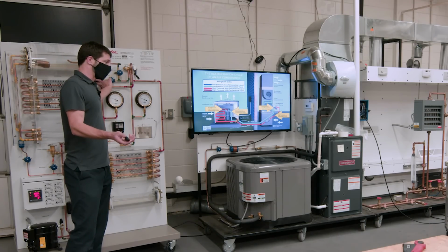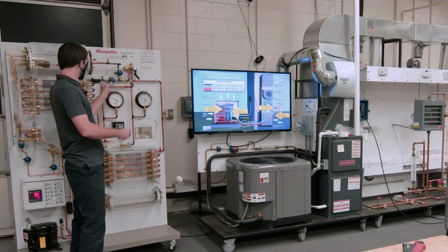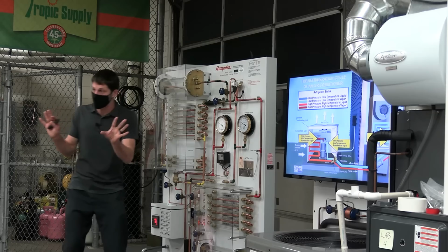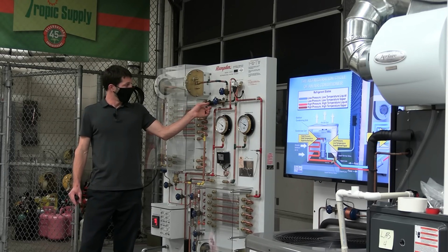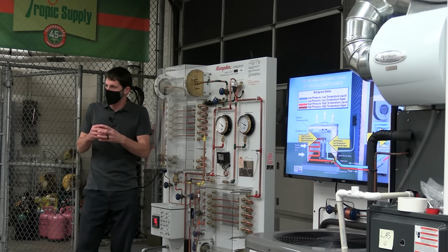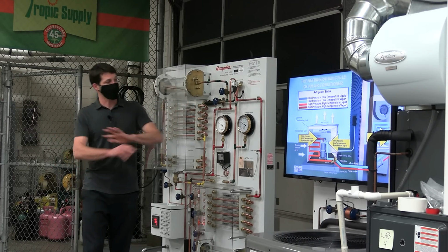Some people may not recommend this, but you can use a standard stainless steel, kind of garden hose clamp, to mount these. The problem with that is people stay away from it because you could accidentally over tighten the bulb onto the tubing and crush it, and then you're going to end up with a leak. But you want to make sure that that bulb has good surface contact.